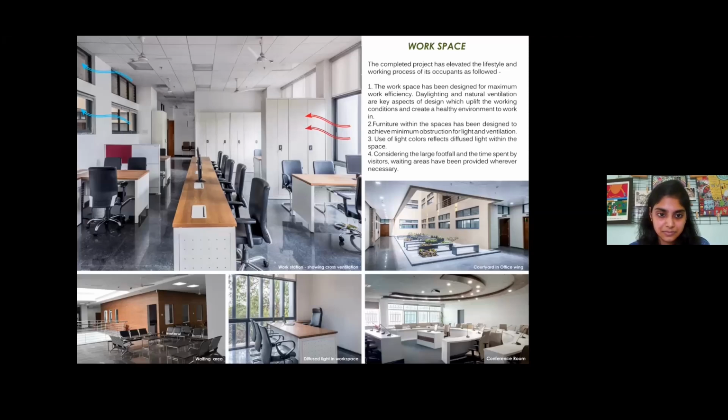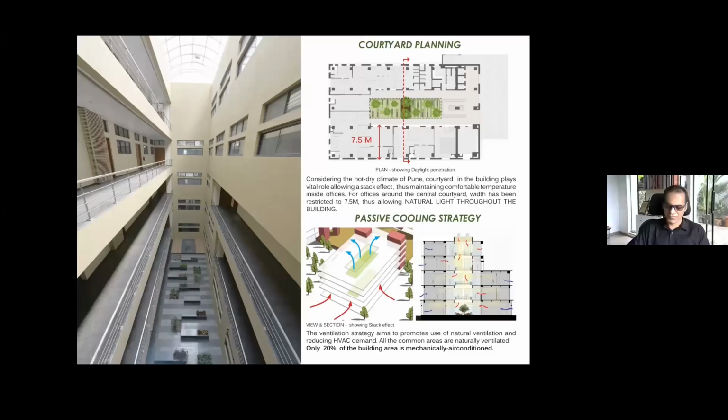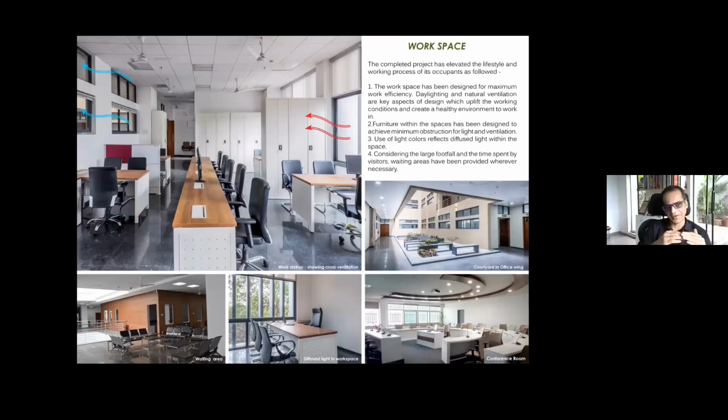It sucks the air, or hot air goes up and it sucks it out, and as it throws it out, the air is sucked in from the windows. So that stack effect is not a new concept, but if you apply it properly, it gives you a very good natural ventilation system. So if you see in this image how it is shown, like the window to your right where the air is pulled in, and it is pulled into the courtyard to the left side window, where the left side windows are having the corridor to that side. So the windows are at higher level to actually have the privacy from the corridor.